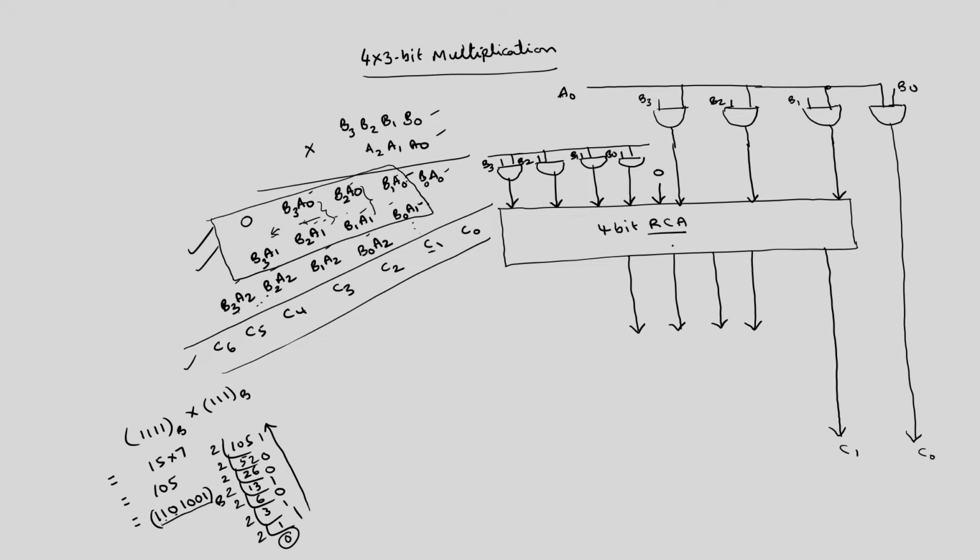So in total, this is the sum bits, and this is the carry out. Total 5 bits will be available. In that, 1 bit will be directly taken as the output. The remaining 4 bits will be given to the adder. Then here I can insert a 0. Then I will perform addition of these 4 bits from here to here using another ripple carry adder.